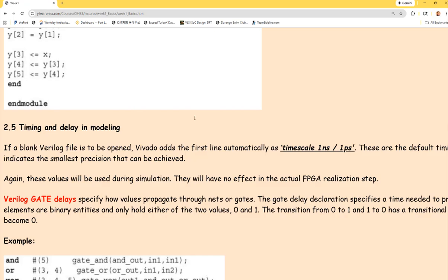Can you use blocking and non-blocking assignments in data flow and behavioral blocks? Non-blocking is for behavioral in general. Blocking, you have to add an assign to it if you are doing data flow. For structural, it doesn't have that kind of mechanism. It's just a gate structure.